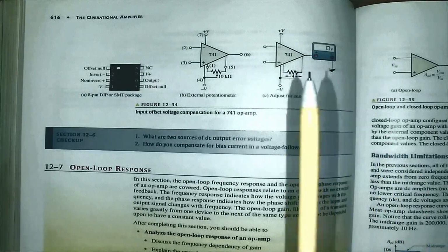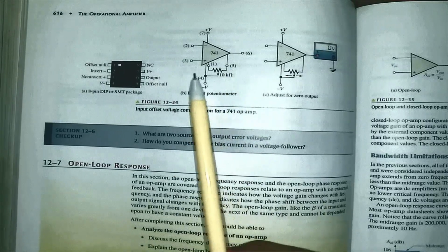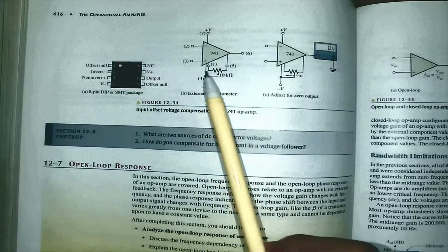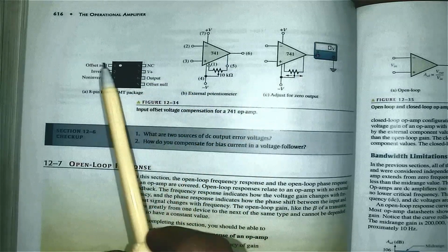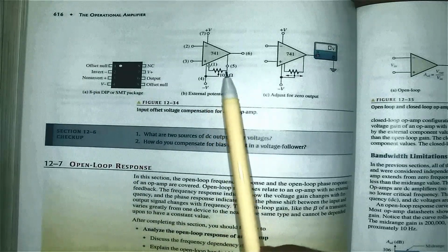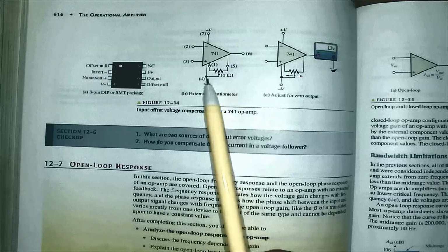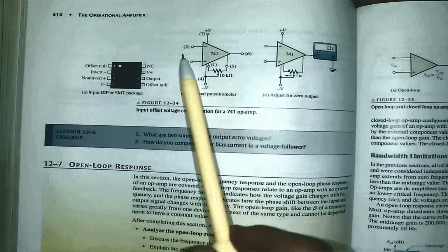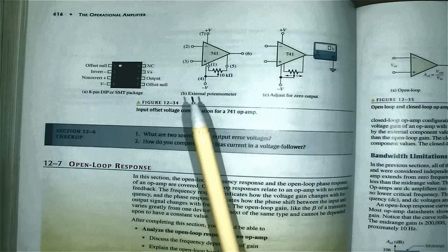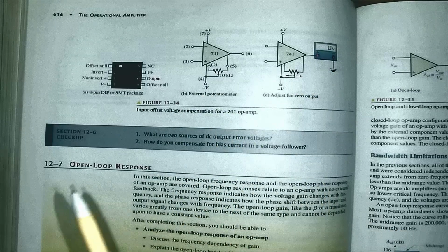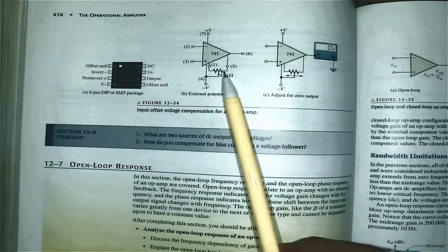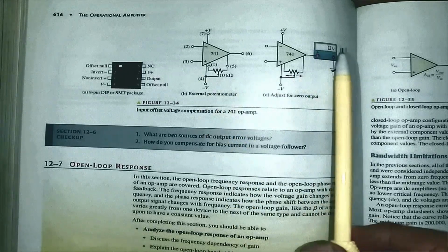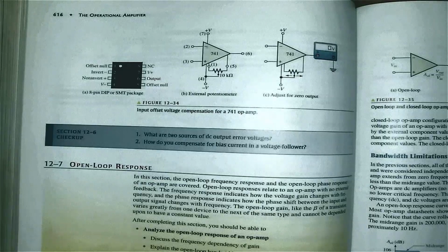In the case of the 741 op-amp, we also have a facility built into this device where we can use pin 1 and pin 5, which they call the offset null. We just take a potentiometer from my negative supply voltage and adjust it to make the output 0. That is internally built into this op-amp device. We can do that by putting that 10K potentiometer there to the negative supply and adjusting it so that if my input is 0, my output is also 0.